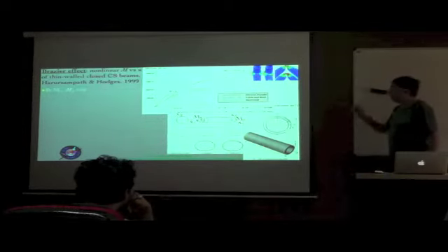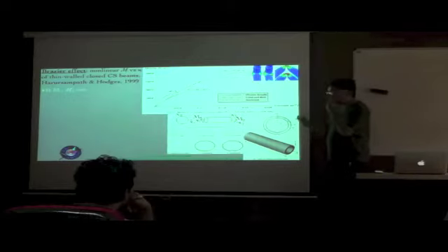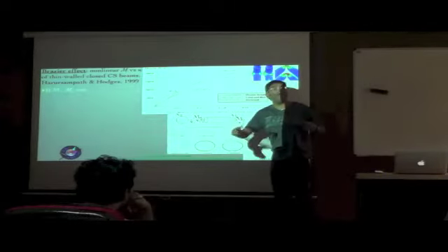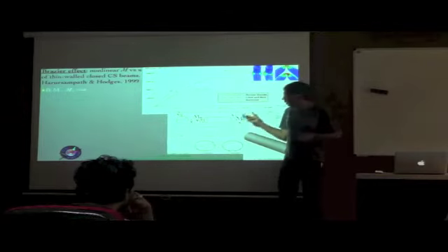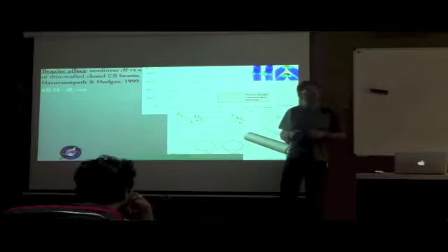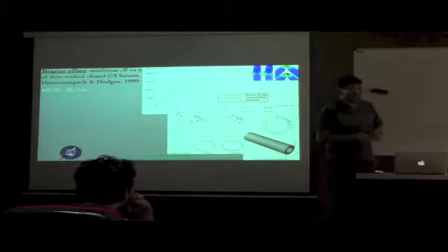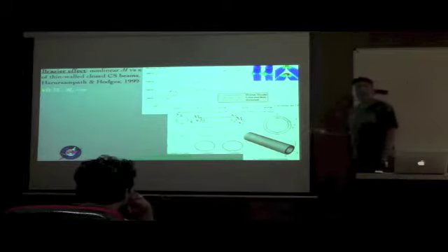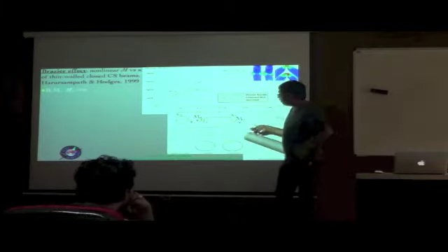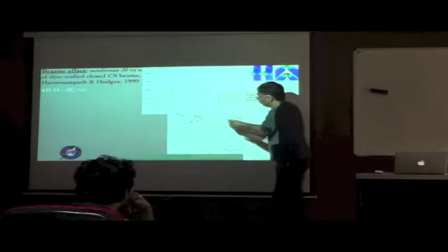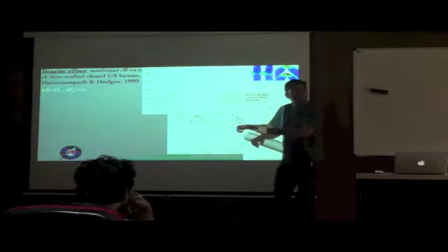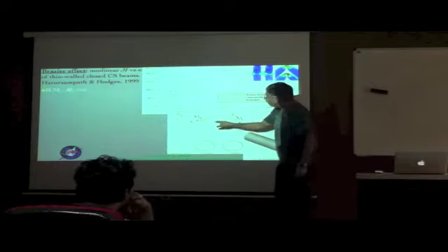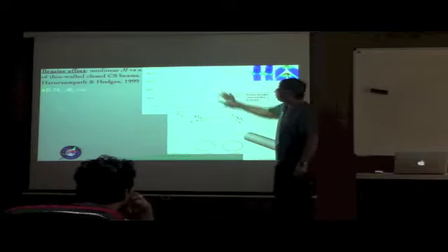But one interesting thing to observe is that when you apply this to real life structures, this is not the only failure that is there for this particular structure with this particular loading. It can so happen, for example, that the material fails, or that local instabilities arise, because remember that the top portion is under tension whereas the bottom portion is under compression. So there can be local buckling taking place, which is not what this is.